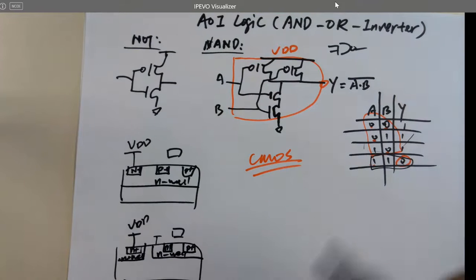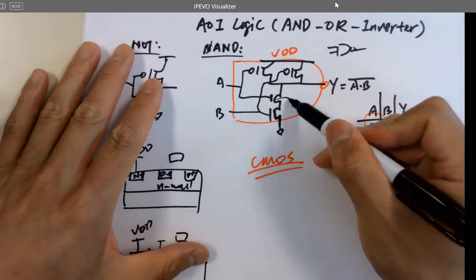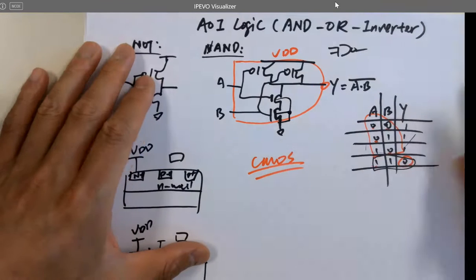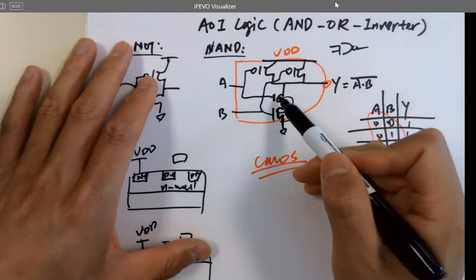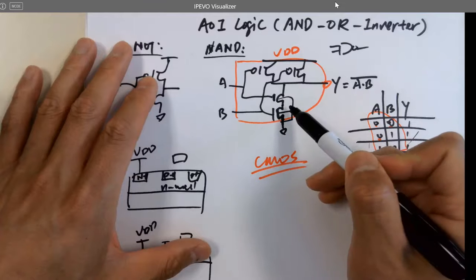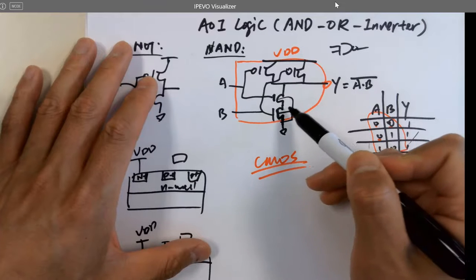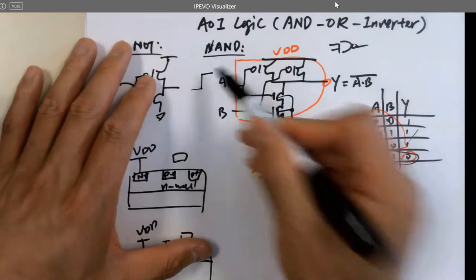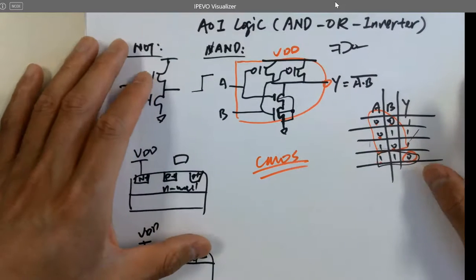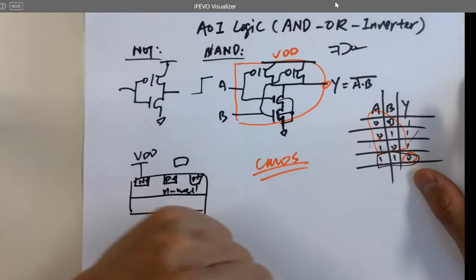The body on the first NMOS, do we give it its own ground contact, or can we just short it straight down? Yeah. Okay. But this one does have a body effect because the source is not shorted to the body contact. It has a higher threshold voltage, but it doesn't matter since these are either 0 and 5. Can always turn it on or off. No problem.